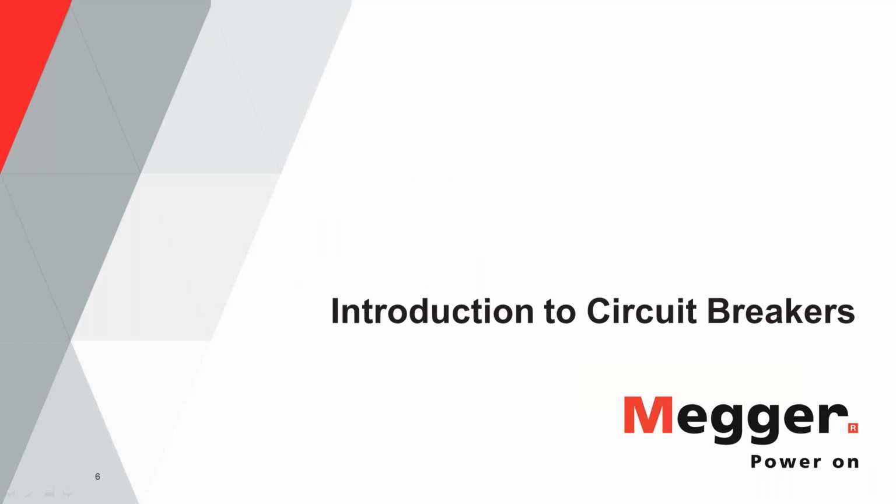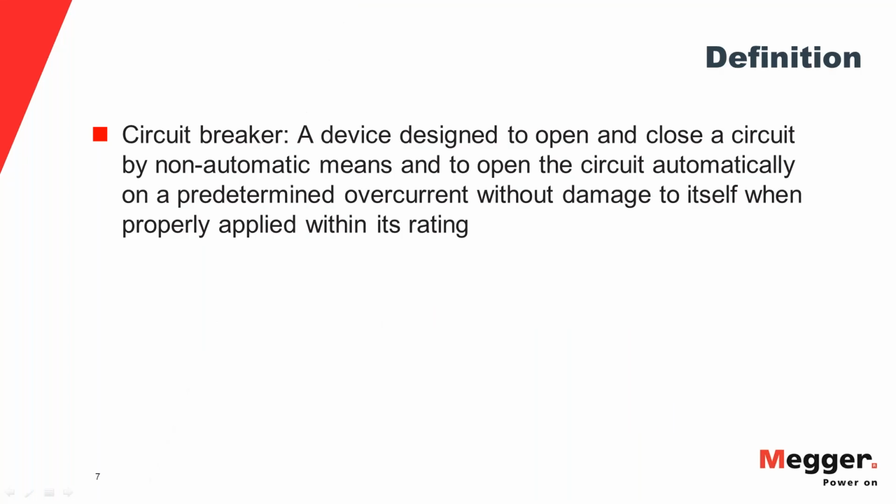So what are circuit breakers? Circuit breakers form the arm of the protection system, I feel. CTs, PTs act as the eyes of the protection system. So the CT sees the fault current and feeds it into the relay. The relay is the brain of the protection system, and the relay operates the breaker, which isolates the fault by interrupting the current.